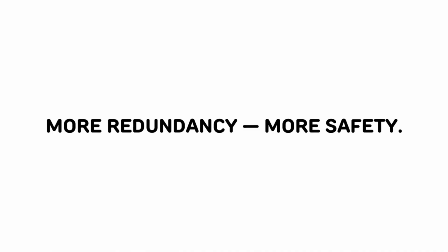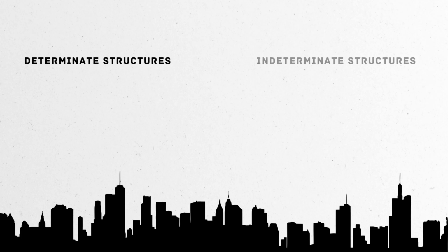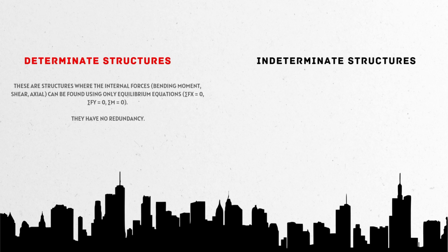More redundancy, more safety. Now, let's talk about something every structure falls into. Determinate structures and indeterminate structures. First, determinate structures. These are structures where all internal forces, bending moment, shear, axial force, can be found using equilibrium equations alone. Sum of forces equals 0. Sum of moments equals 0. That's it. No extra equations, no backup paths.